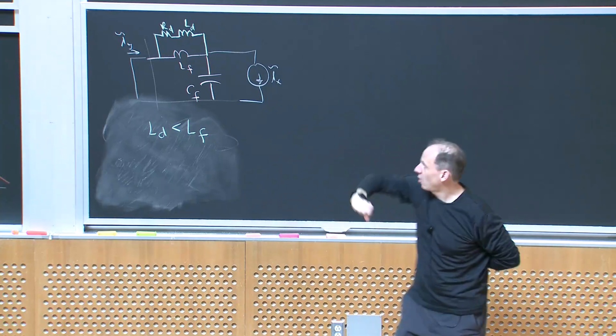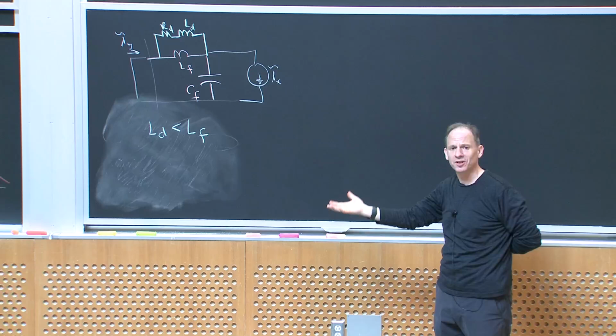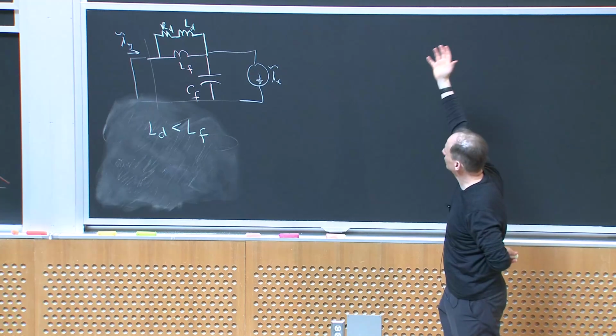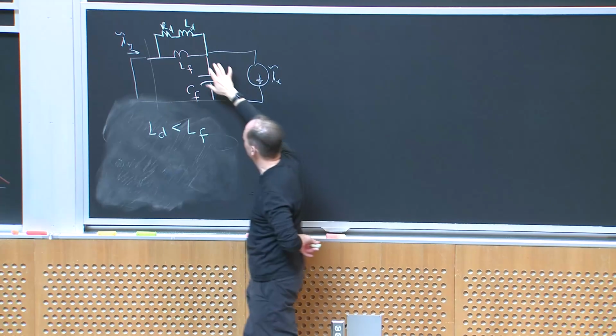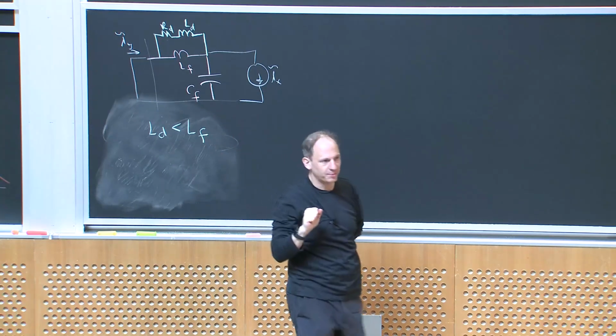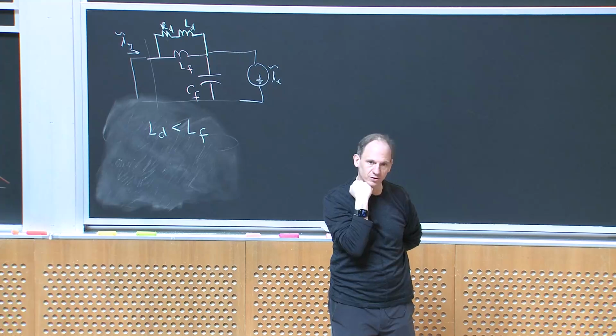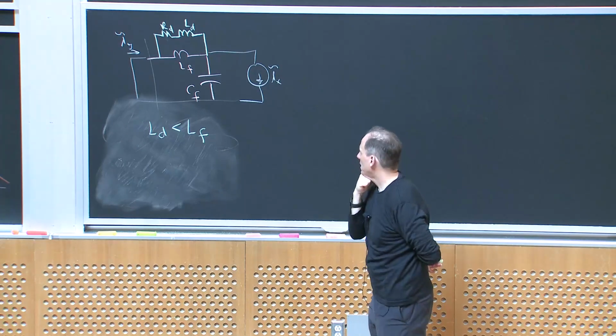Now, this is also a very popular damping scheme, and you can do the same thing for this analysis. For a given value of LD relative to LF, there's always going to be an optimum value of RD to give you good damping.